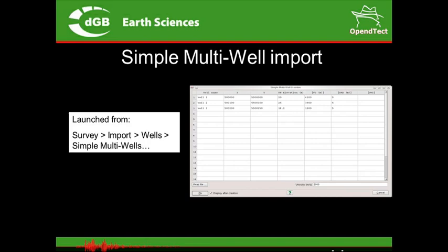So this utility window will allow you the quick creation of multiple vertical wells with a constant velocity, as you can see here, as a time depth model provider. You can do it manually or create a file, and then in one go you have all your wells. What you will really need are: well name, XY, and Kelly bushing elevation.